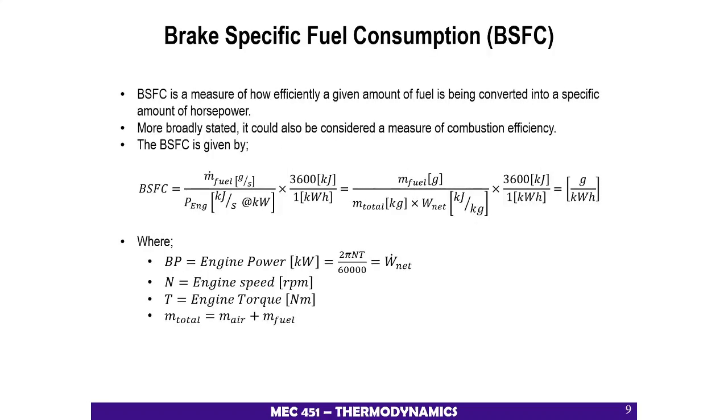Brake specific fuel consumption, BSFC. BSFC is a measure of how efficiently a given amount of fuel is being converted into a specific amount of horsepower. So more broadly stated, it could also be considered a measure of combustion efficiency. So the BSFC is given by this formula.